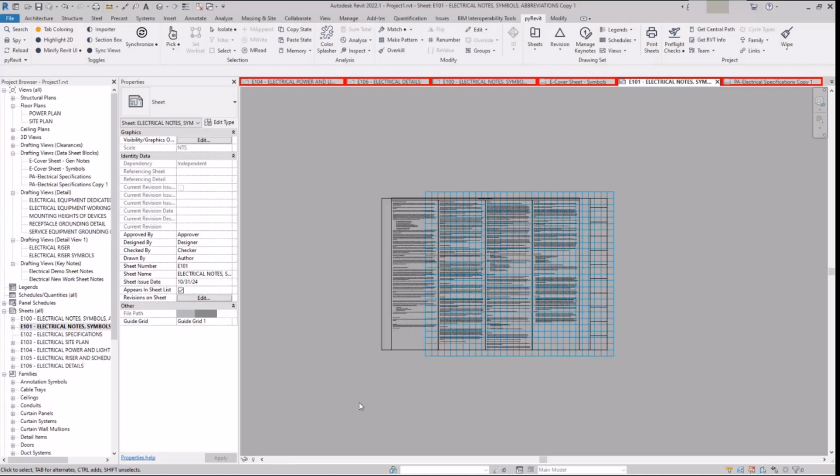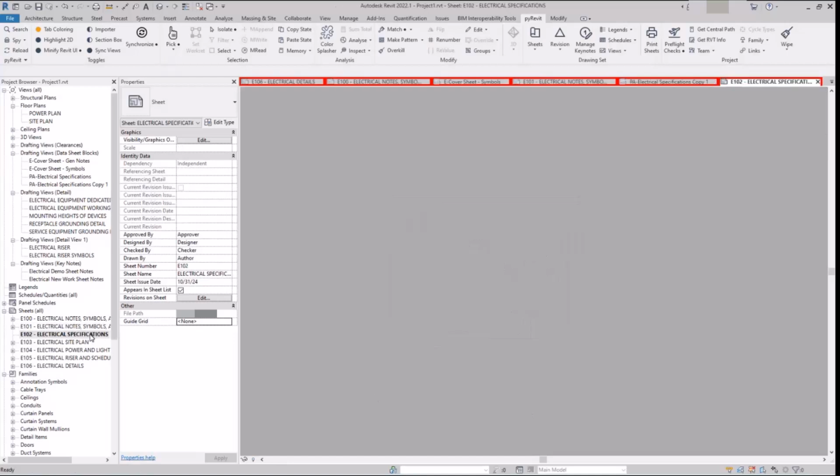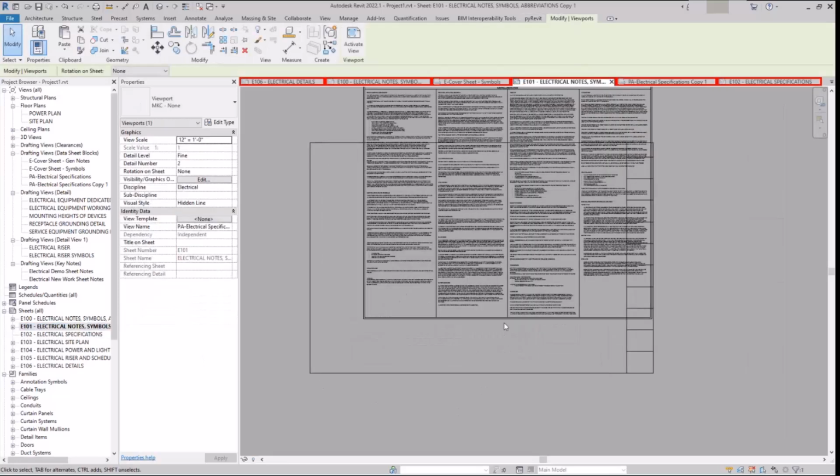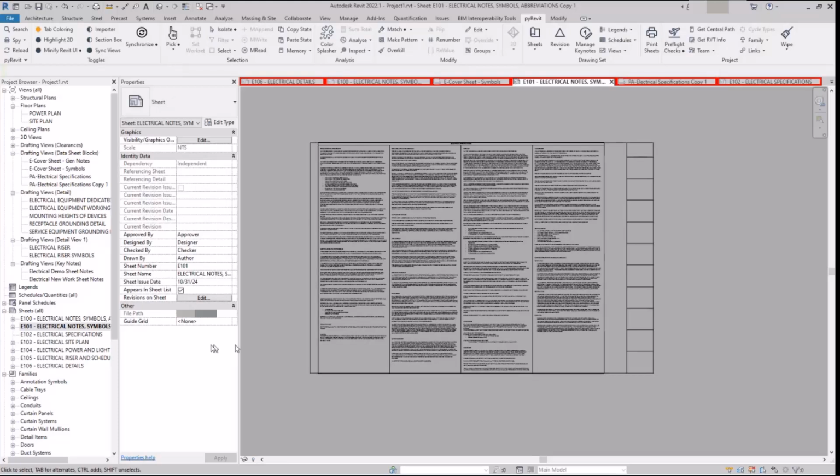You, as the designer, the engineer of record, whoever, before you push this up the chain of command or seal it, you want to review this so that you're not having stupid things that somebody else is calling out that you should have caught. So you're going to put on what's called your drafting hat, then you're going to put on your engineering hat, and then you're going to put on your contractor's hat. Those are the 3 hats. So you're going to go through this with a drafter's eye and look: is it off kilter? Is it not squared up? Does it look wrong in the PDF?